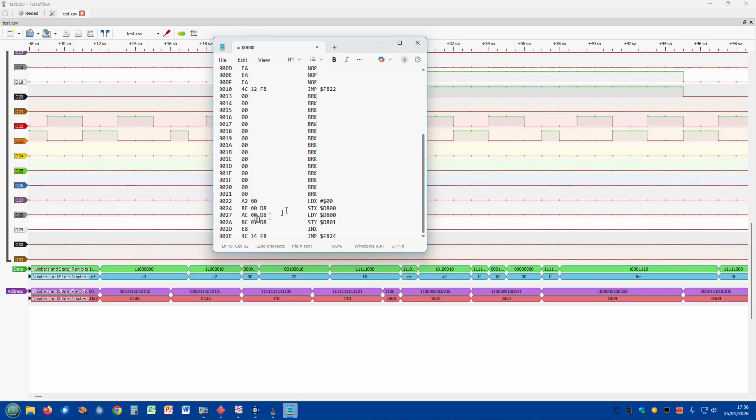Next instruction is 8E. There we go. That's the next instruction, which is coming from this 23, which is for the 0. Phase 2, loading the 0. This is just the bits changing state. And a new address in there of 24. So at 24, we've got 8E. There's 8E getting strobed in there. So that's the next instruction, which is store X into the next address.